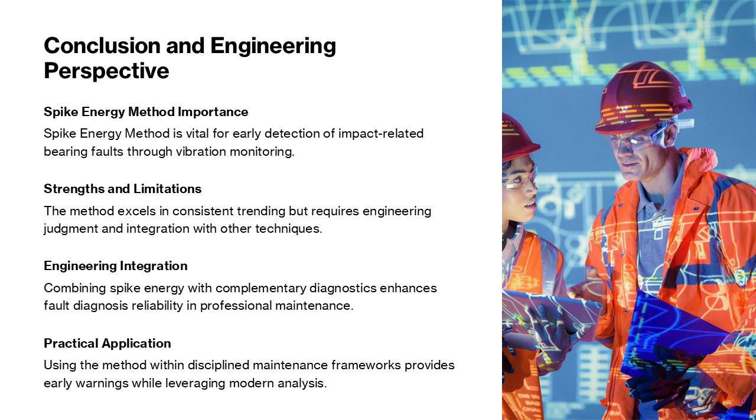It provides a simple and effective means of detecting impact-related bearing faults, particularly in their early stages. While modern diagnostic techniques offer greater detail and robustness, spike energy continues to deliver value when used correctly and interpreted with engineering judgment. Its greatest strength lies in consistent trending rather than absolute thresholds. Engineers should understand both its capabilities and its limitations, integrating it with complementary analysis methods to achieve reliable fault diagnosis. By applying the method within a disciplined and professional maintenance framework, organizations can continue to benefit from its early warning capabilities while leveraging modern advancements in vibration analysis.